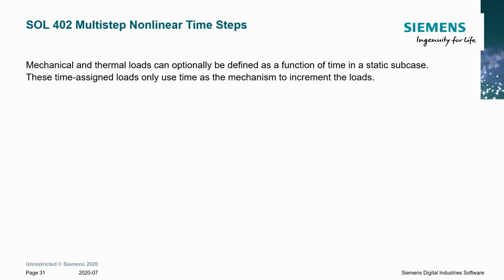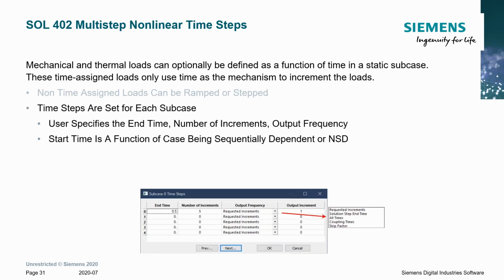All right. So as far as nonlinear time steps in 402, mechanical and thermal loads can be defined as a function of time in a static subcase. And these time assigned loads can only use time as the mechanism to increment loads. Okay, non-time assigned loads can be ramped or stepped.